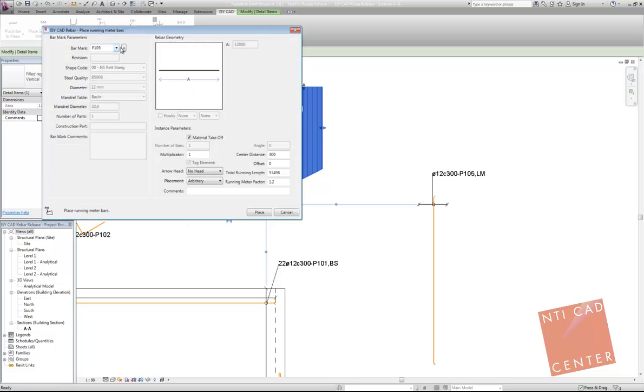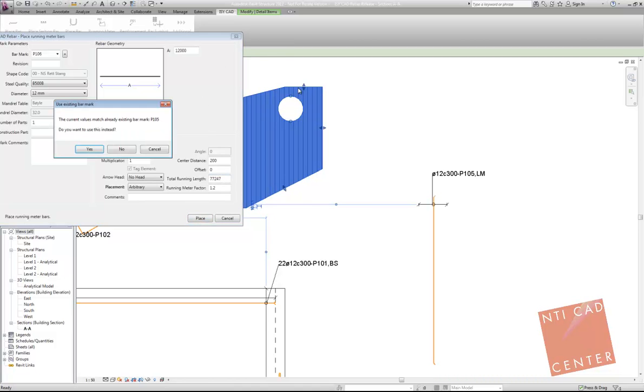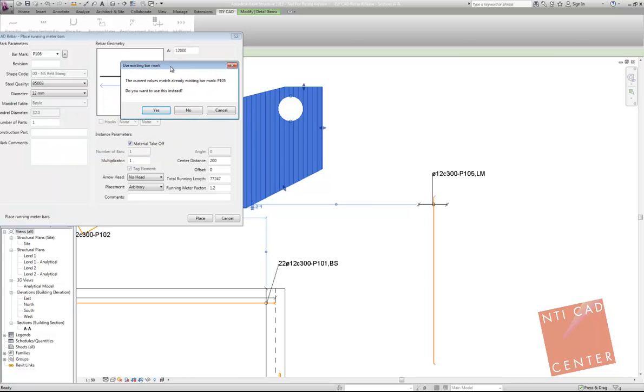and you will see that, let's create a new position, and what you will see basically is that it calculates the total running length. So if I change, for example, spacing, it will recalculate the total running length. So this total amount of reinforcement will be actually calculated for this area selected. So yeah, that's one of the other functionality which is very nice.